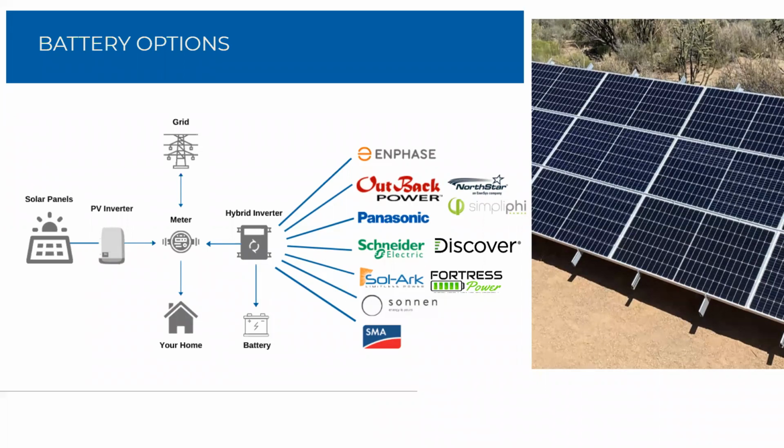And EV charging, I don't want to be such a pessimist, but in some ways, EV charging is not super compatible with solar. Fast chargers draw, I want to say, up to 60 amps. For 60 amps at a given time, that is in no way, shape, or form compatible with a battery or with performing off grid. I think with a slow charger, sure, you have 120 volts pulling 5 amps, that's fine. That's a load that could be managed by a battery. But if we're really looking at 60 amps for 30 minutes to 2 hours, like, no way, Jose.